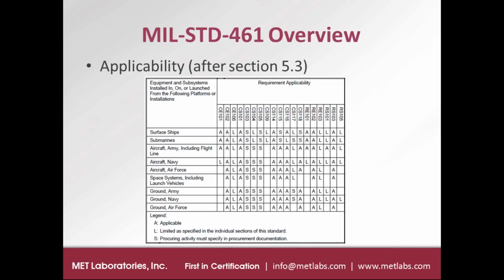In those cases, MET does offer to follow this applicability table and recommend tests, and where a specific list isn't provided. Where there's an L in the applicability table, you have to refer to that specific section of the standard to read the more detailed criteria of whether the test is applicable to a given device or not. And then the S represents that those tests are only applicable where the procuring activity of the military has specifically listed that that test is required on a specific contract.